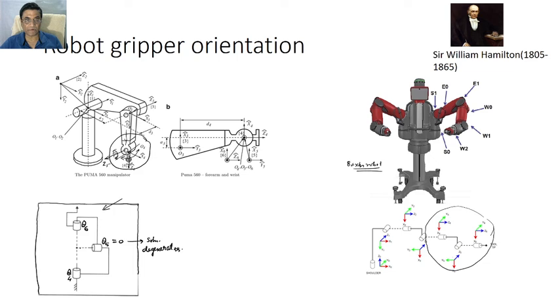And that will happen when the torque momentarily becomes extremely high to rotate this motor, to take it out of the gimbal lock situation. So those are not good for the robot. So we need to avoid singular configuration, right? This is also called singularity when gimbal lock happens.